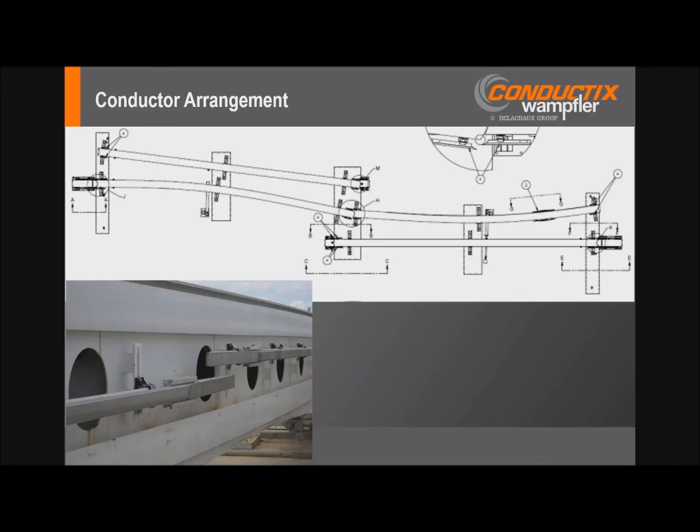And it also requires the reversal of power phases in the power rail. That's essentially what we're showing down here. In this switch assembly, this crossover switch, where we would have a tangent condition, as we go into crossover mode, we have to incorporate this phase reversal element in the conductors to switch the phasing.